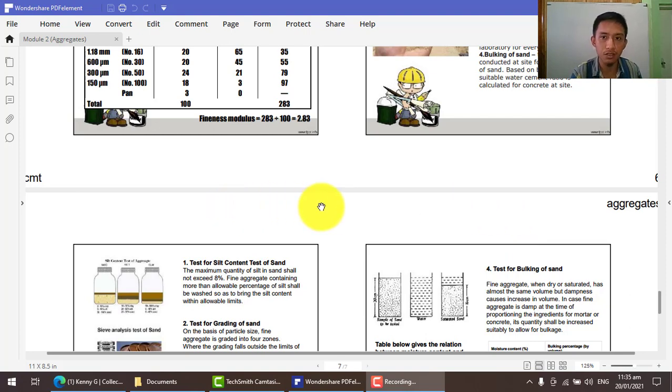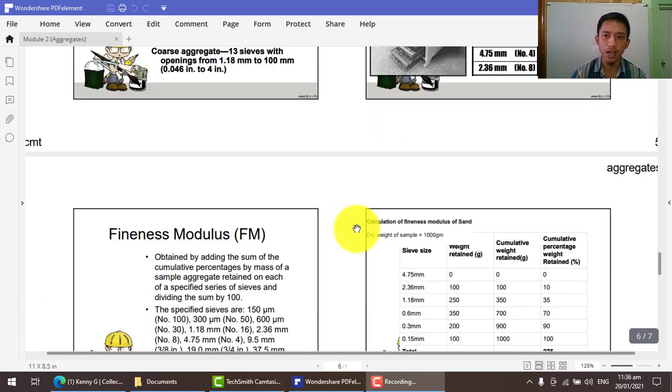But for a very big construction, let's say a high rise, the testing of the aggregates to be used in the concrete mix should be very strict, because the strength of each material used in a high rise is critical. For a small construction, it is okay not to focus much on this, as long as the strength is satisfied, not every property. So that is for aggregates.